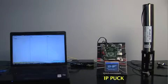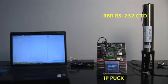In addition to the IP PUC board, demo hardware components include a commercial RBR data logger with conductivity, temperature, and pressure sensors connected to the board's serial port. Note that this instrument itself doesn't implement any standard protocols. Instead, it's operated by a manufacturer-defined command protocol through the serial port. The laptop on the left is connected to the IP PUC board through an Ethernet switch.